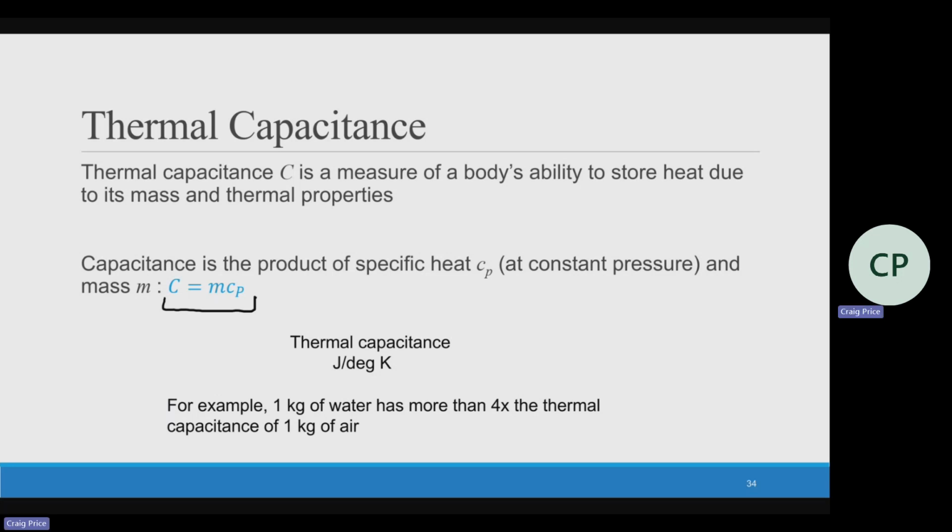Questions? Those are my two elements: capacitance and resistance. And then from there, I'm just looking at, okay, let me model it. I've got a box. What's coming in? What's leaving? And we can try to figure out what the temperature is, because that's our goal, is to figure out what our temperature will be as a function of time. When will we reach steady state, and so forth.